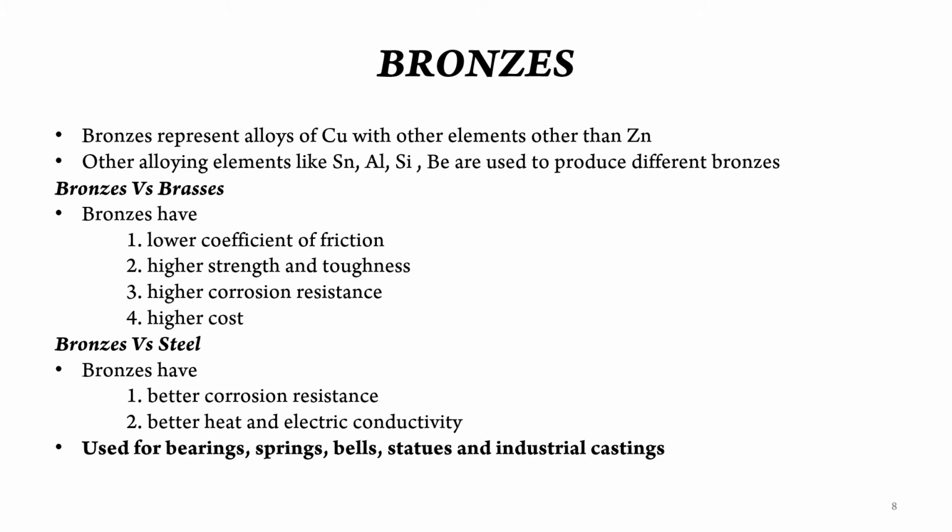Bronzes have lower coefficient of friction, higher strength and toughness, higher corrosion resistance and higher cost. അതുപോലെ ബ്രോൺസും സ്റ്റീലും കൂടെ ഒന്ന് കമ്പയർ ചെയ്ത് നോക്കാം. Bronze has better corrosion resistance and better heat and electrical conductivity. They are used for bearings, springs, belts, statues and industrial castings.